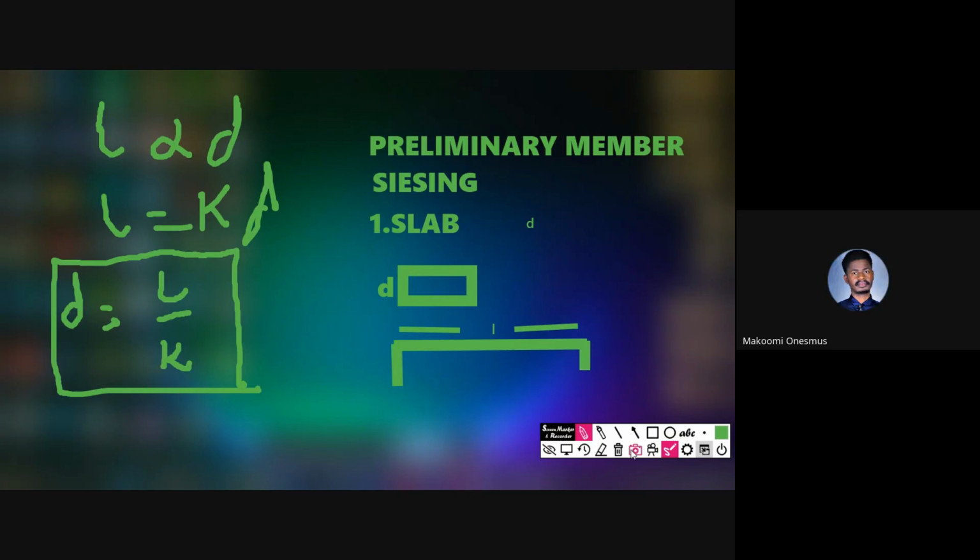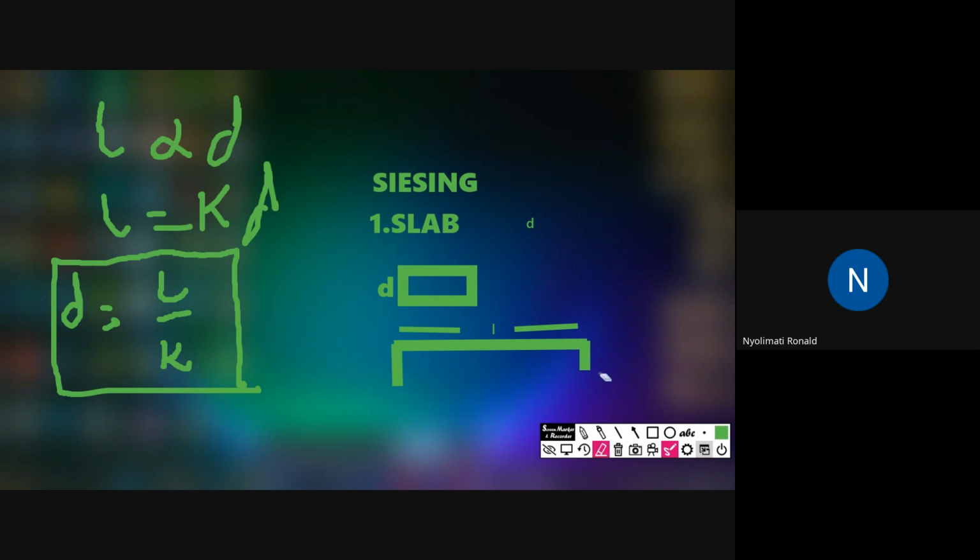And the Eurocode says, let me write it here: D equals L divided by K. And Eurocode says this K, which is constant for slab, ranges from 24 to 30. Okay? Yes.